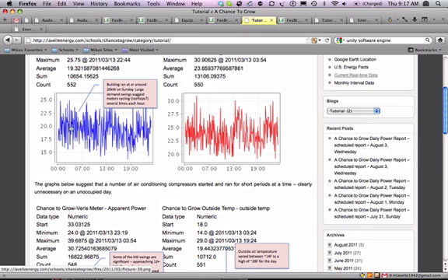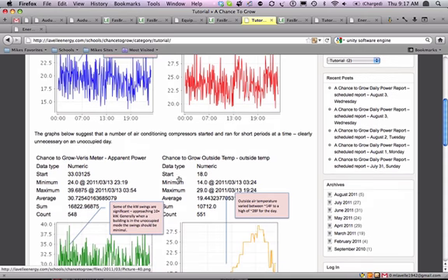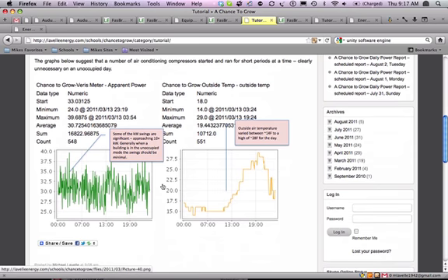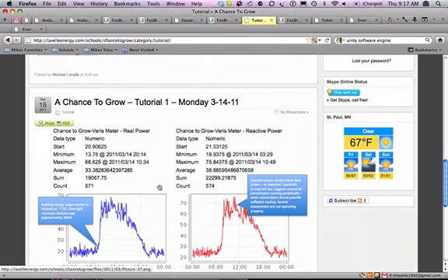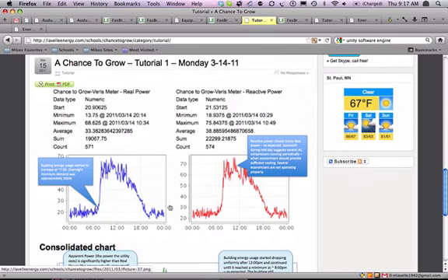Now, the magnitude of the changes may indicate that it's nothing more than the fans themselves that are cycling. But several of them have to cycle at the right time in order to get this kind of an approach. Some of the kW swings are significant, approaching 10 kW, when the motors themselves are probably half a kW to 1 kW. Here's some more indication of what's been going on in the building.